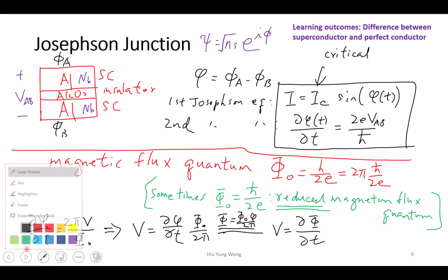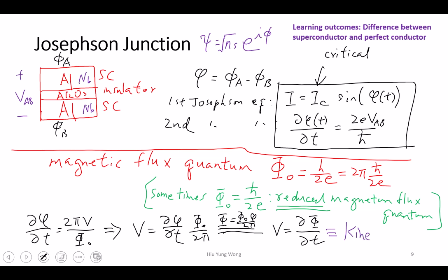However, this is not the regular inductance. Regular inductance comes from the storage of magnetic field. This is called kinetic inductance. One way to think about this is that I'm a superconductor. There's no scattering. The Cooper pair will just fly. You are not going to stop that. They have this inertia. In a regular inductance, you just wait, they dissipate, and then the current will go.